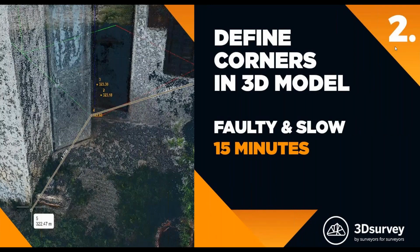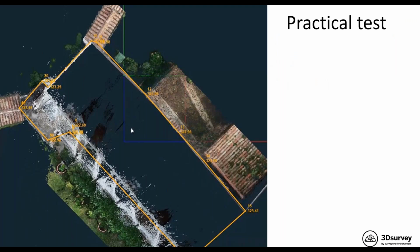The second option we have is to define these building corners in 3D. It's faster than measuring them with a total station, but it can be prone to errors because we can easily click on the wrong point in the point cloud. I have a practical demonstration here. Let's try to draw an outline of a complicated building in 3D survey.